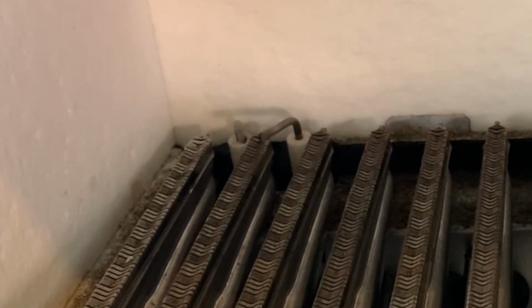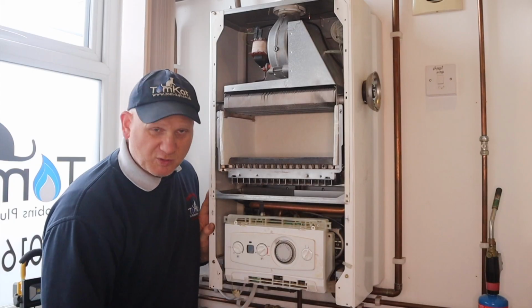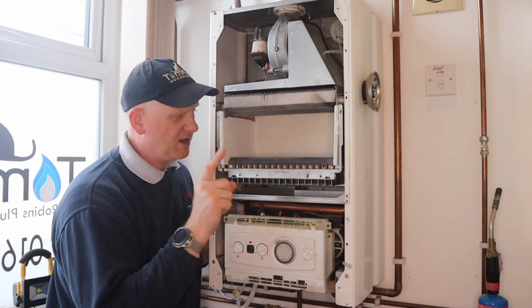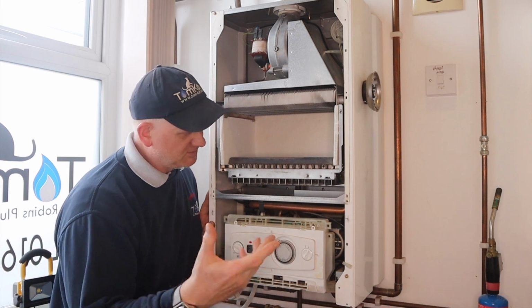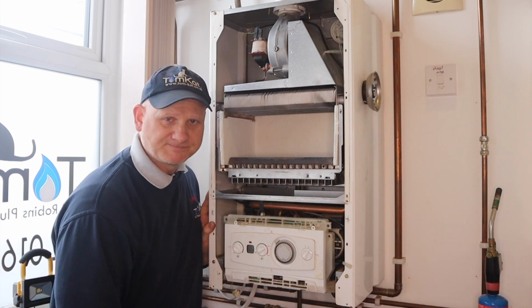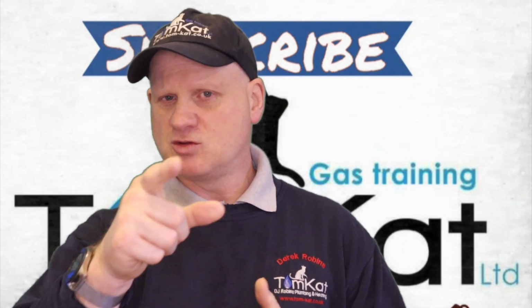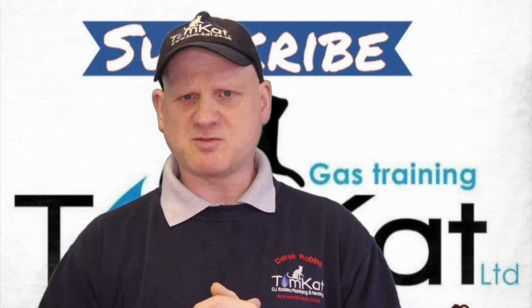So could you see it was still clicking? And it's put the F1 fault on. So that's what would happen if flame rectification hadn't worked. And that is the end of this video on the sequence of operation of a gas boiler.